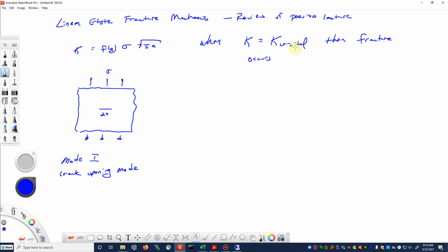We also had some lectures where I asked you to take a look at either the derivation of the equations for the stress fields ahead of the crack tip or the plastic zone shape ahead of the crack tip, so we can take a look at those as well. Just as a refresher, if we were to put a coordinate system at the tip of a crack, and plot the stress sigma against the radial distance from the tip of the crack, we would typically see something that goes like this shape with those equations. And the stress would tend to infinity.